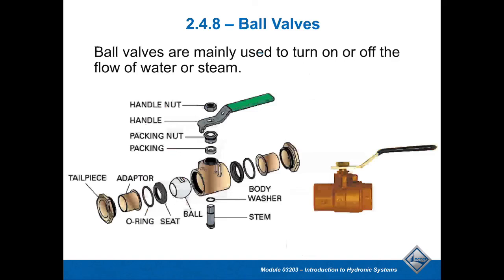Another valve that's a little more common for isolation nowadays, and also for flow, would be ball valves. Now, for many years they would say don't ever use a ball valve for controlling flow, but they actually do work, and they've designed a lot of the valves to allow you to control water flow for that.